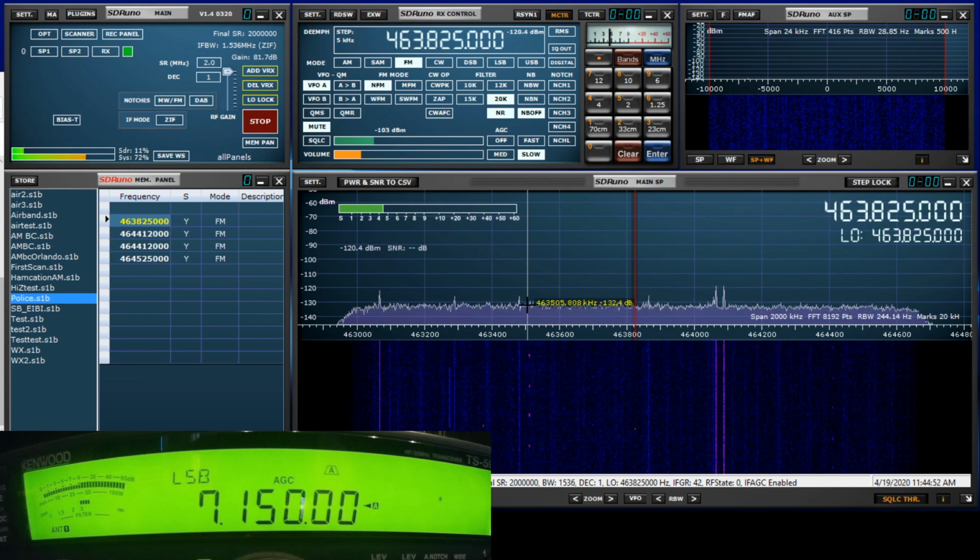Because I have that broad bandwidth output, you will get a fair amount of range if you use an external TR switch. As was pointed out in the comments here, the MFJ switch I showed does have a limitation on how high it can go, in which case you may want to roll your own or use a higher frequency splitter and some other means of protecting the RSP. There is no doubt that if you're using an IF tap on the rig, you will not be able to look at 468 megahertz at the same time. And at this point, it boils down to what you want to get out of your Panadapter.